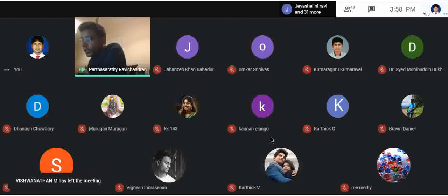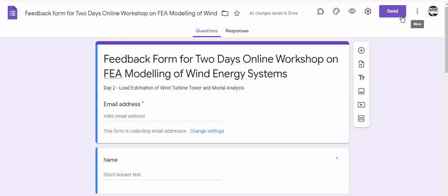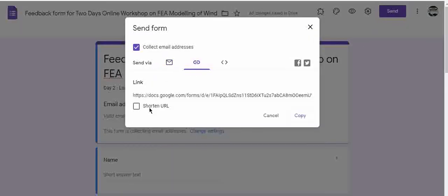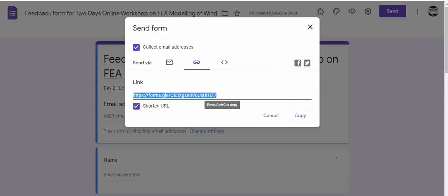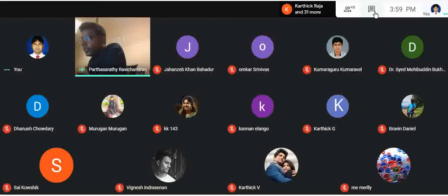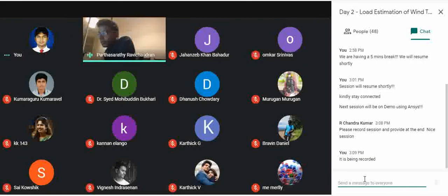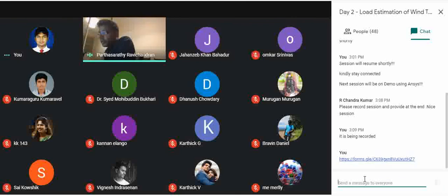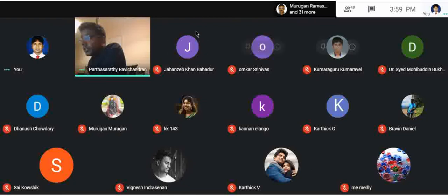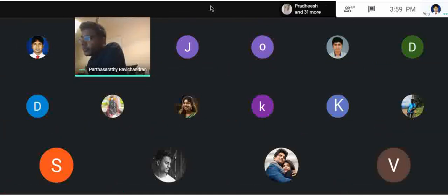In actual practice, you would be doing mid-surface extraction of all these surfaces, then applying the thickness, then meshing of all these components, then applying a single type of material, then a combination of materials. That's how the actual case would be. The demo would take beyond this time, but I was trying to show you a simple structure where I created a cylinder and a taper model combined in one shot rather than having so many shell elements.